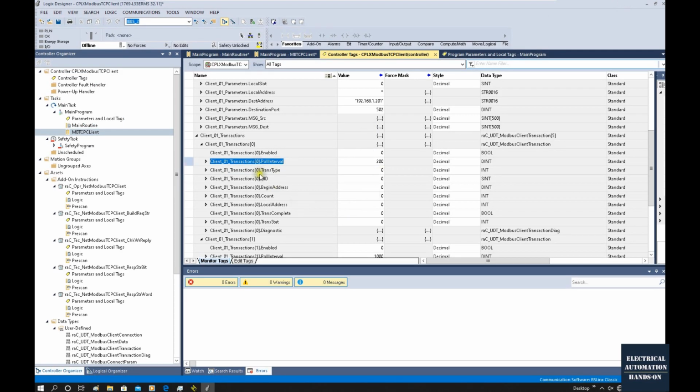From this transaction 0, we will use the 3 here. We will read the data from the server side. Okay, and this UID, keep in mind, this UID is an integer number here. This UID is very important for some third-party modules. So sometimes some manufacturers will preset the value to FF, that is a hex value, the integer value of 255.